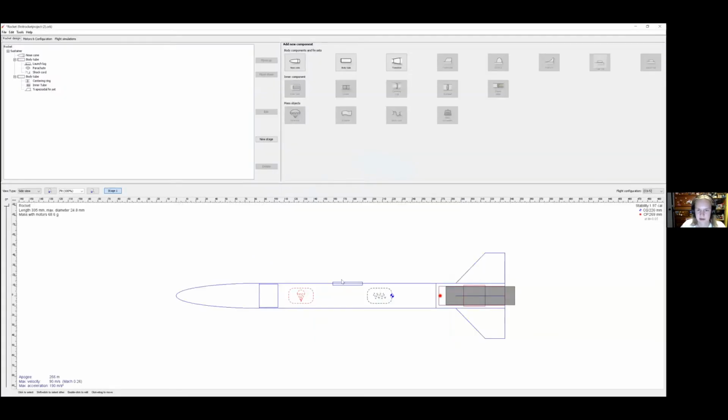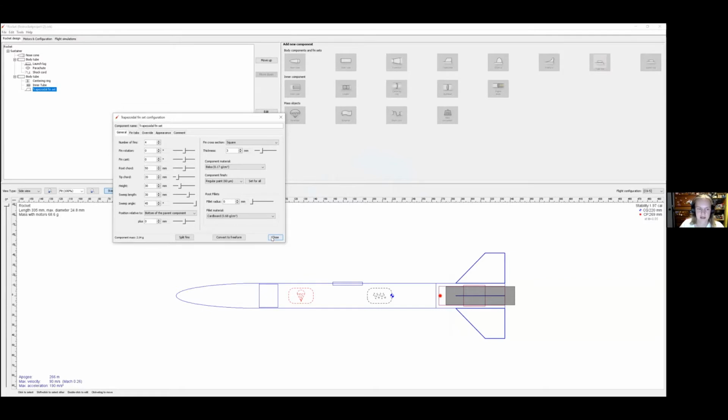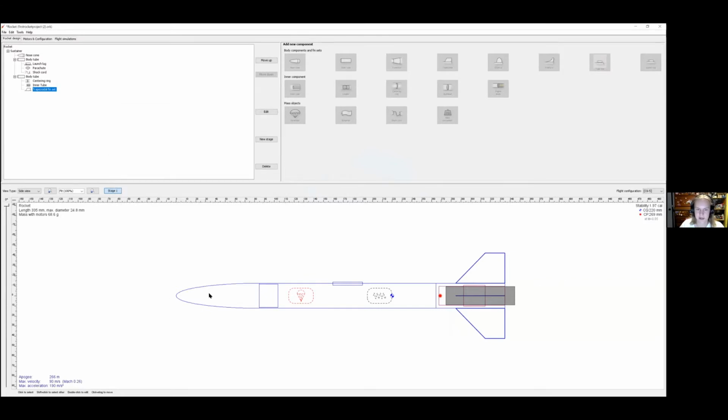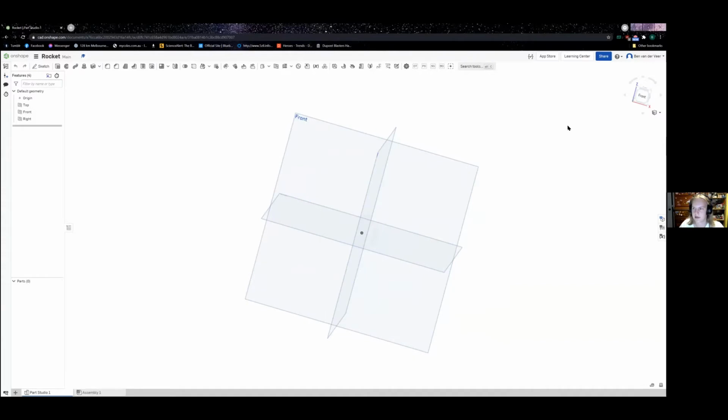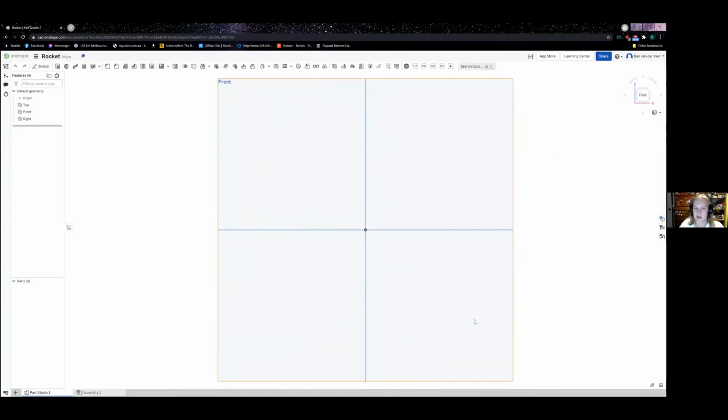Cool. Yeah. Anyway, so basically I'm going to use this as an engineering drawing, which is basically what it is. It's a 2D drawing of a design, and I need to take this drawing, take its measurements, and put it into CAD. This is a very similar thing to what you'd encounter in industry. You'd be working off drawings and getting it ready for manufacture. I will talk a bit as well about how to actually design something for manufacture, in this case 3D printing, because you can't just have any old geometry. You have to have something that can actually be physically made by the method that you are using.